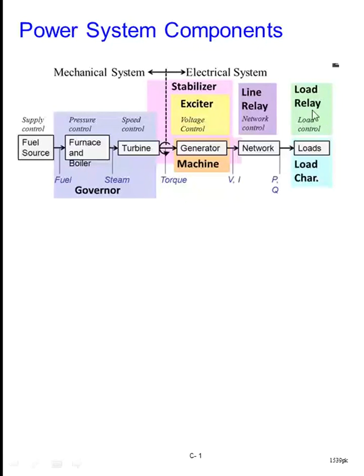So we have a load relay mainly for the load shedding purpose, so that the system remains interconnected, maintains its frequency, and operates in a stable form. So this could be the typical presence of several components in the system that you can consider. Though we have a more complex system, it is not shown on this slide.